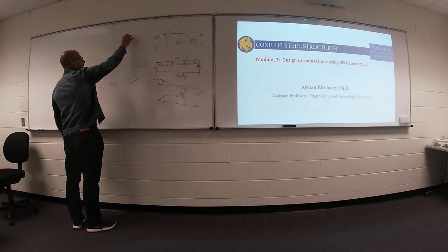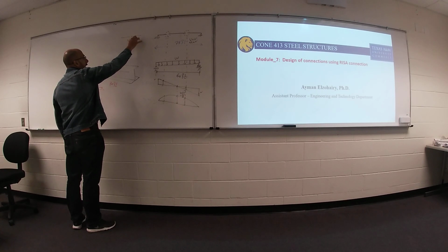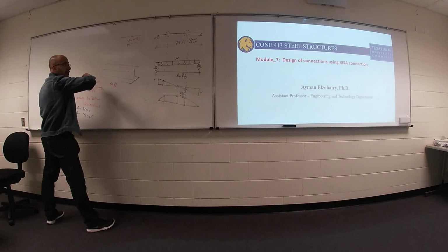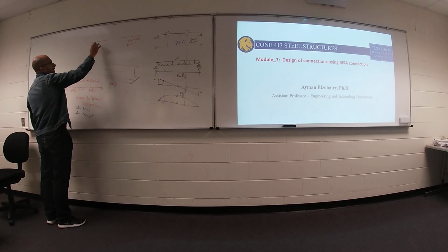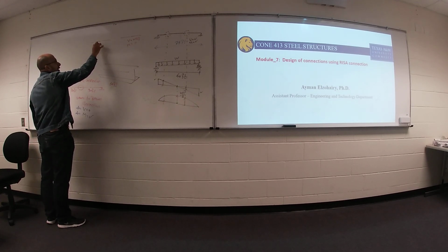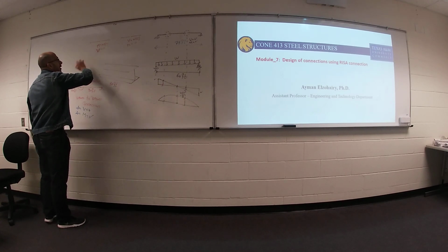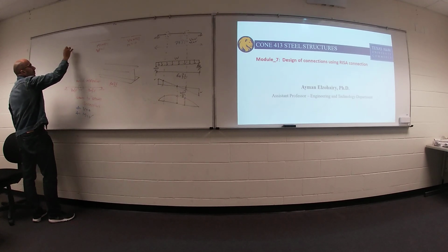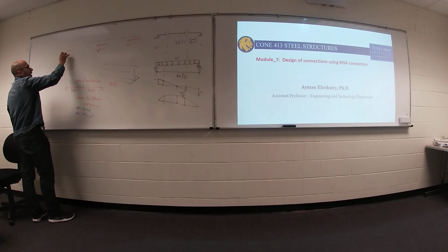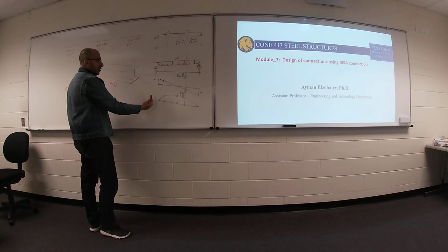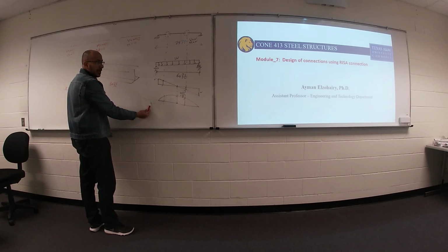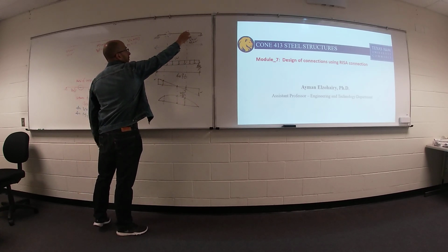Sometimes your connection will be under the effect of shear only and your moment equals 0. Sometimes your connection will be under the effect of moment only and your shear equals 0. Sometimes your connection will be under the effect of moment and shear, based on what is the diagram of your internal forces and where is your connection.